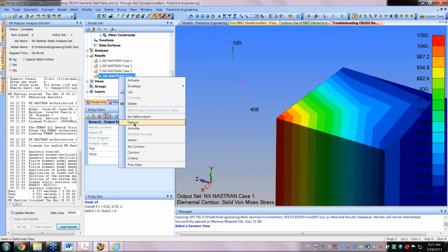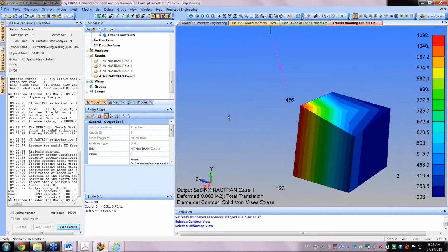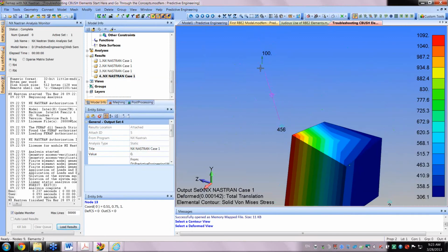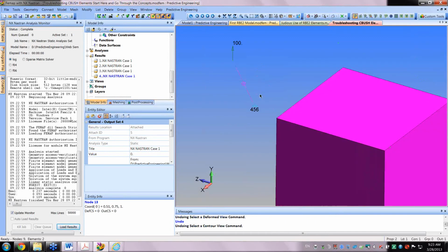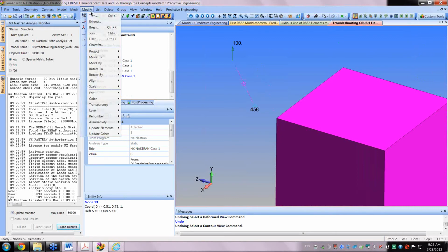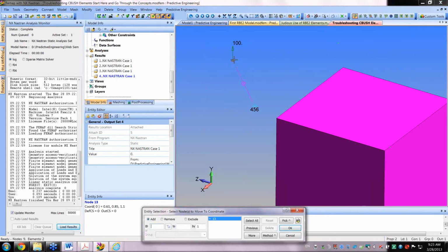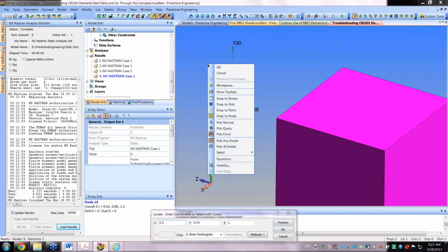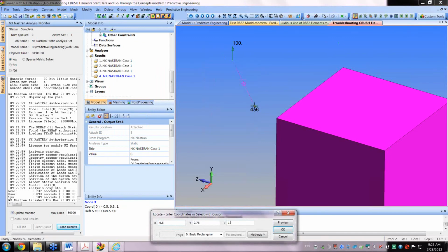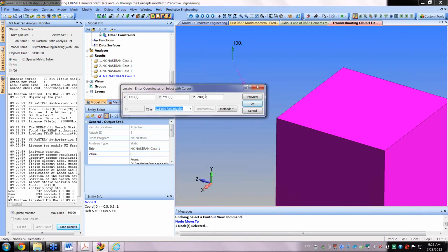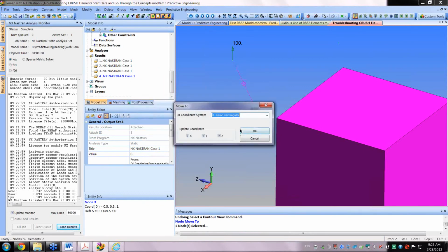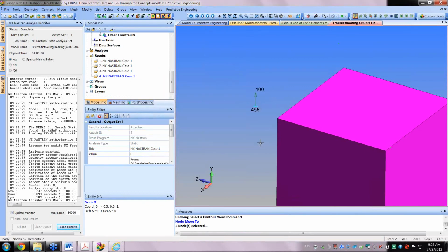Okay. There's one last thing I want to show on this, is that this is with spacing. Okay, I'm going to undo. Well, what if it's coincident? If I make these things move to node, okay, right click, snap to point is enabled. Pick that point right there, it returns that nodal coordinate system. I'm going to move all 3 like that.